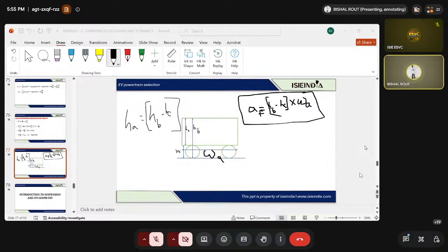Now, while designing a motor, you don't have to take this entire model into the motor design. You can take this torque, speed characteristic and give the output from this particular characteristic to the input of the motors. Then based on that, you can draw anything, right? You can characterize the motor. You can connect a 70 kilowatt motor and see how the motor behaves. You can connect a 30 kilowatt motor and see how the motor behaves. All those things you can do. Fine. So this is all about vehicle dynamics using MATLAB specifically, right?